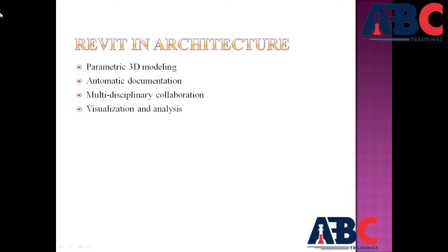It also has more beneficial things, such as automatic documentation, like 2D drawings, from the plans and the sections to schedules and details, which are automatically generated. If you update the model, it will be associated to all the views, and it will give you seamless design work that is applicable all over your model. For example, if you delete some walls or doors from one view, it will be automatically updated in all other views, and it has so many benefits for the drawings.